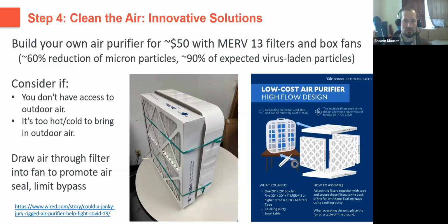Something important to note, you want that filter on the inlet side of the fan so it's drawn sealed against the face of that fan, and that limits filtration bypass.